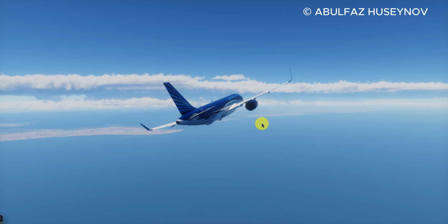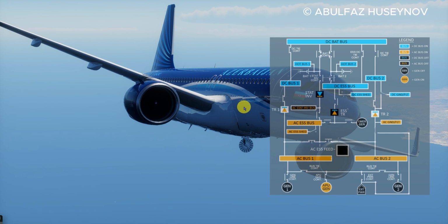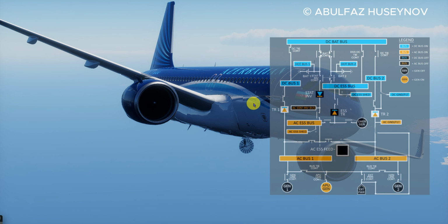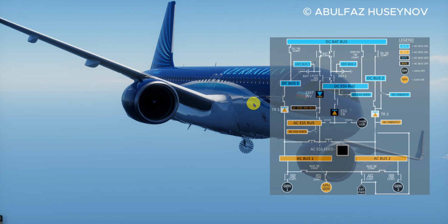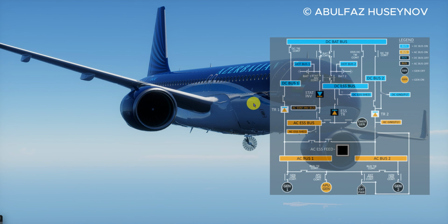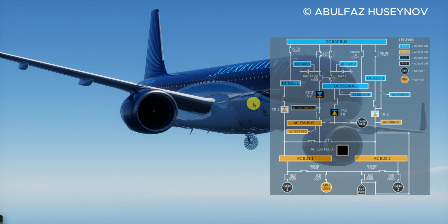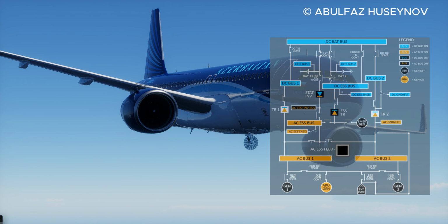Direct current is a type of electrical current that flows consistently in one direction. In Airbus aircraft, DC power is primarily used for critical systems such as avionics, flight control systems, and emergency equipment. The DC power is supplied by engine-driven generators known as integrated drive generators (IDGs) or by auxiliary power units (APUs). These systems provide stable and reliable power essential for flight control and navigation, ensuring continuous operation even in the event of an engine failure.